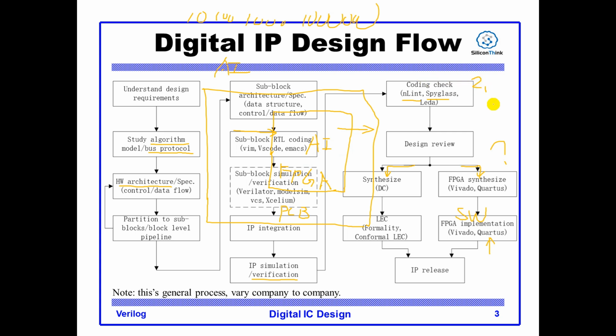The second reason is, in this step, we will put the function in a real silicon device. Yes, the FPGA device is a real silicon device. And for other steps, such as the simulation step, the simulation is just running in the EDA tools, not in the physical environment. So the FPGA emulation will give you more confidence about your design. That is, if the design can run on an FPGA device, you will have more confidence that the design will run on ASIC chips.